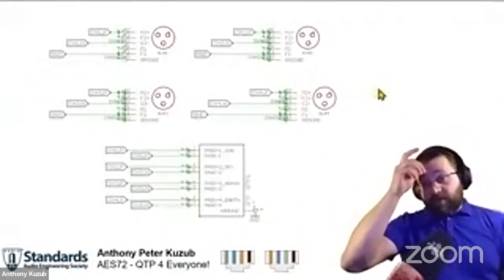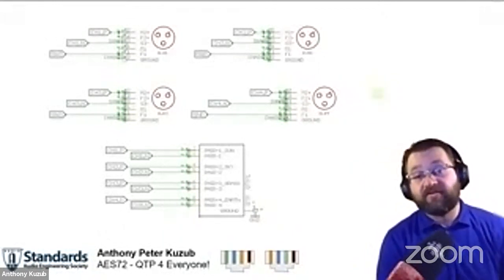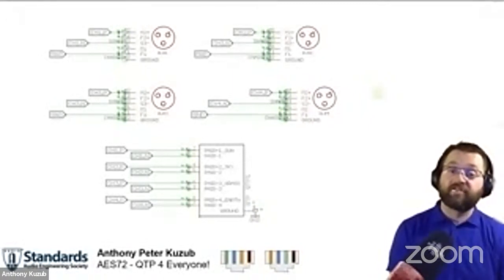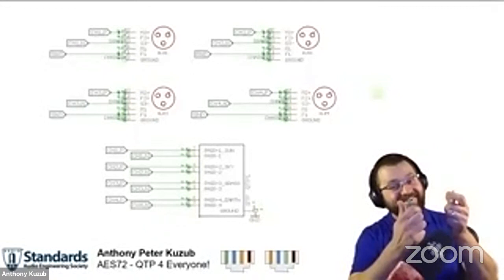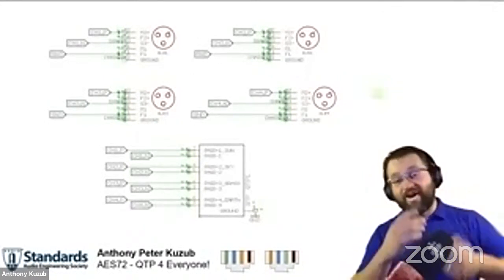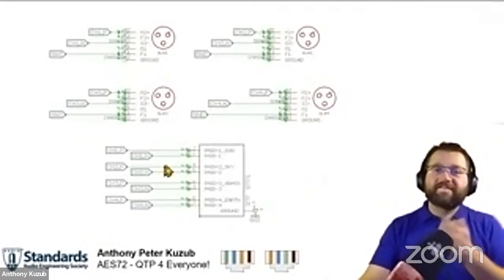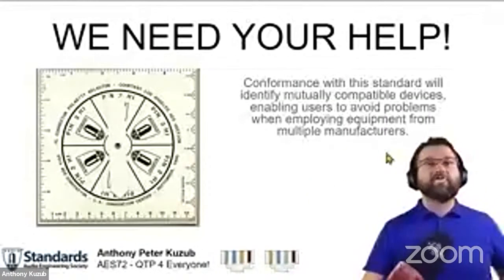And it's very simple. You look at what the XLRs used to be, both male and female, and there's a positive and there's a non-inverting, right? And then there's a ground. And with something like this, which is the RJ45 AP8C type of connector, you can map 4 channels one to one.